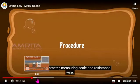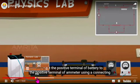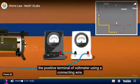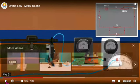Procedure: connect the positive terminal of a battery to the positive terminal of the ammeter using a connecting wire. Connect the negative terminal of the ammeter to the positive terminal of the voltmeter using a connecting wire. The negative terminal of the voltmeter is connected to the upper terminal of the rheostat.